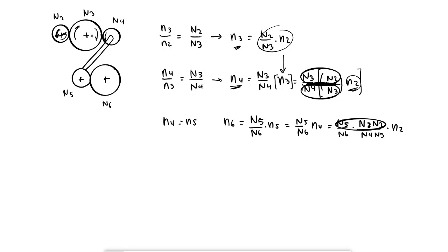So again, if I just want, for example, N3 in terms of the rest, and I'm starting from N6, because for some reason I know the rotation of 6 right here, it would be N6 times what? From the relationship, I know that there's going to be an N6 on the numerator, not the denominator, and N6 is one that is being driven.